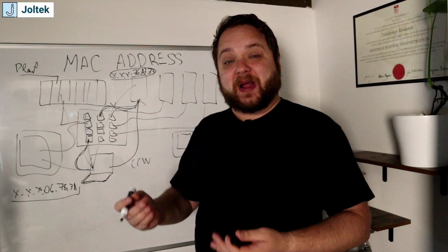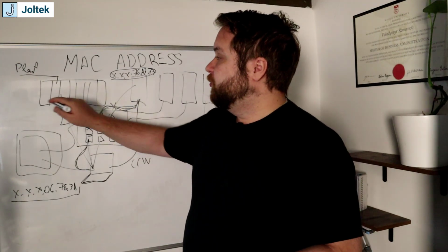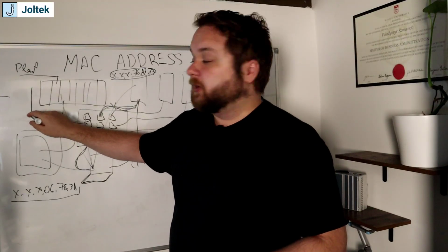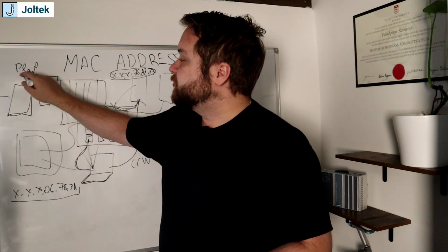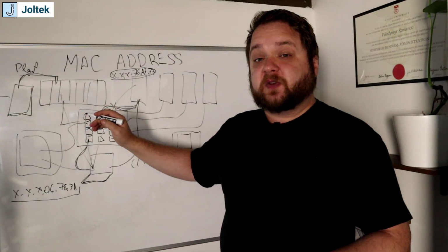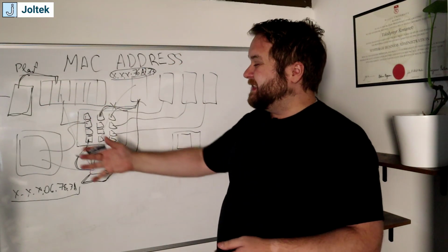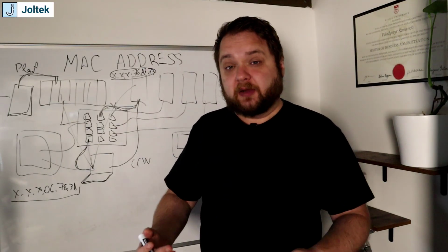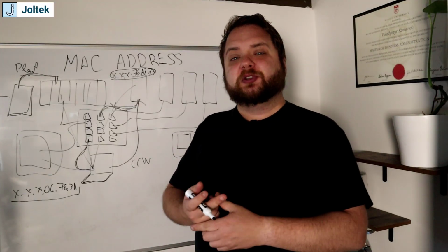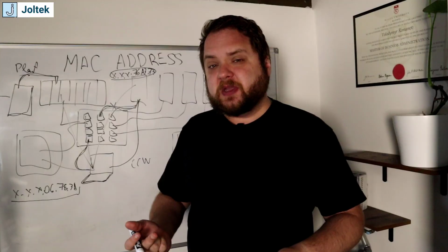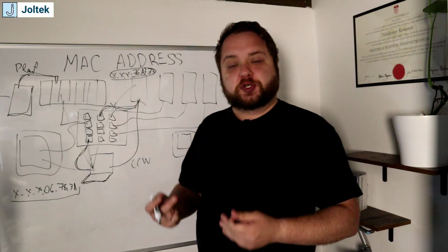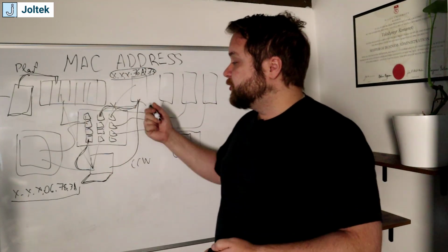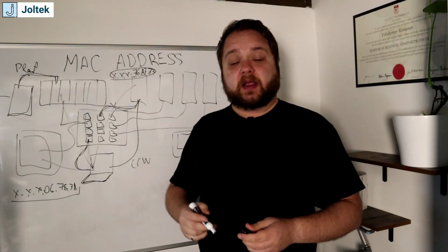This is also a problem compounded by the fact that a lot of times you will have, for example, a server rack here, right? I don't know how well you can see this, but maybe I'll draw it a little bit here. So you have a server that's going to connect at the plant level to that specific PLC. And not only are you going to see this architecture, you're also going to see a lot of different architectures at the plant level. So you have multiple VLANs, you have multiple machines potentially with the same IP address. And so the only way for you to ensure that you're pushing your changes and updates to the right, not only controller, but also peripherals, is to make sure that the MAC addresses match.